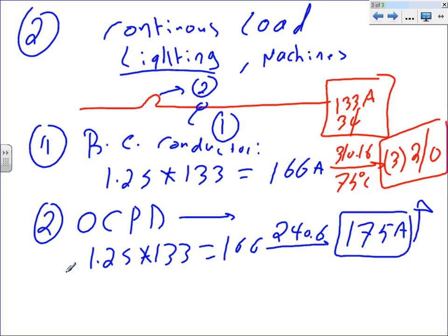That's like if you have a load that is 100 amp or larger, and you need to group it with another 100 amp or larger. You can put it in a bigger conduit. Bad idea. You can, but it's a bad idea. Why is it a bad idea? You end up with a lot of derating. You're going to derate the conductors, bigger conductors.